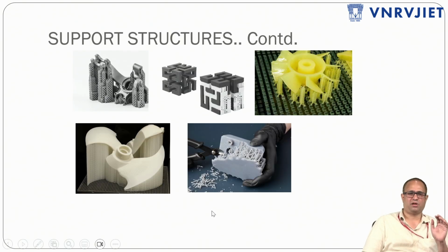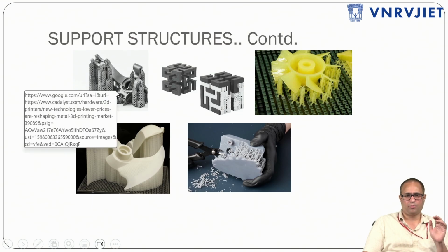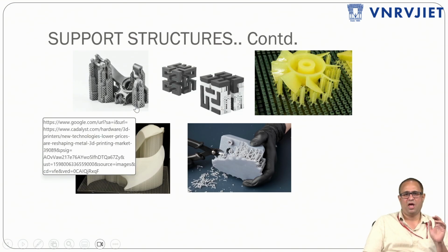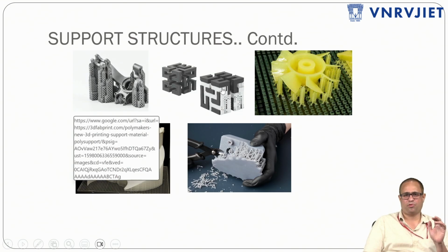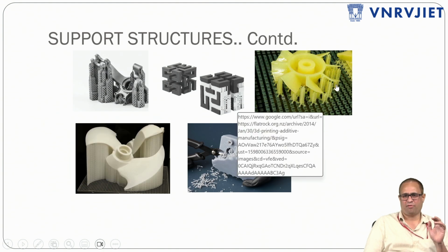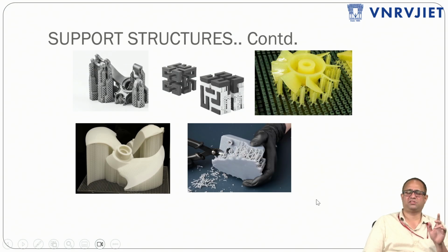So you can see the support materials. You can see this for metal 3D printing: the supports obviously look like lattice structures, and this is the support for polymer printing. For polymer, you can see the support complexity because these overhangs are going to be subject to supports, for the FDM process or the SLA process. We are going to use different tools to remove the supports, so I can say that this is a breakaway support.